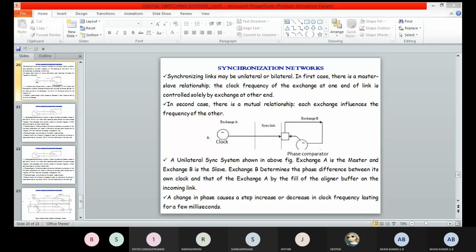Same thing here also. We are using two time switches, and in between we are using the space switches. How to make the cross point between these M incoming and M outgoing highways is through these space switches only. There are M incoming and M outgoing PCM highways. These should be connected to the time switches, and then the incoming and outgoing time switches are connected by the space switches, that is the M into N crosspoints, which will be represented by B switches.